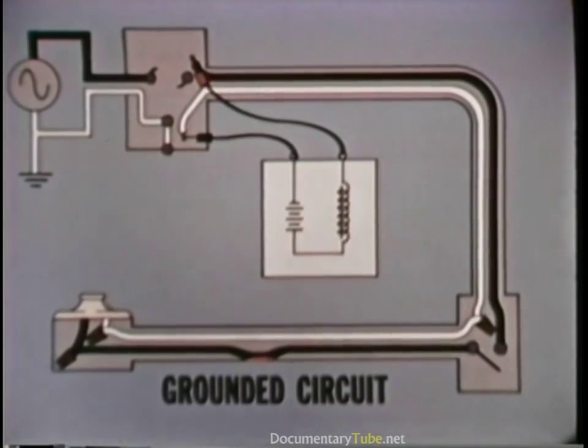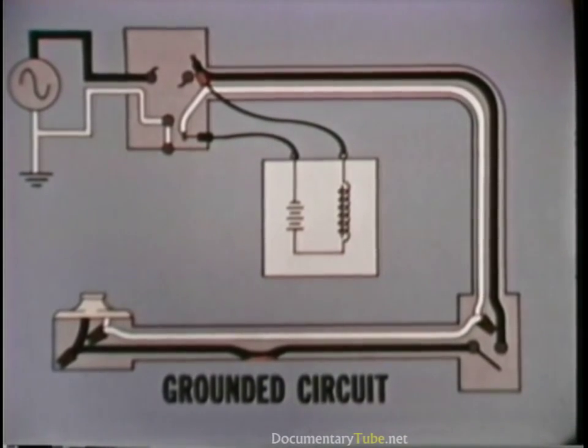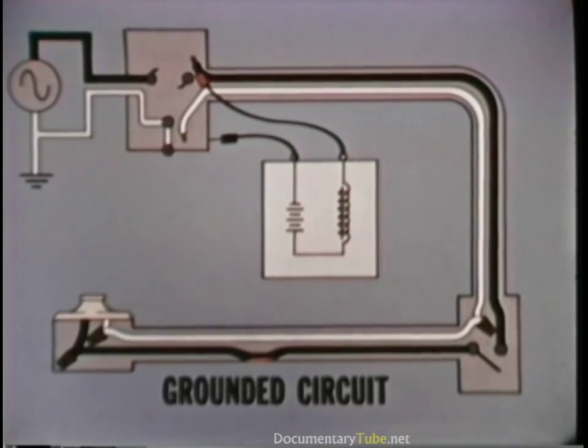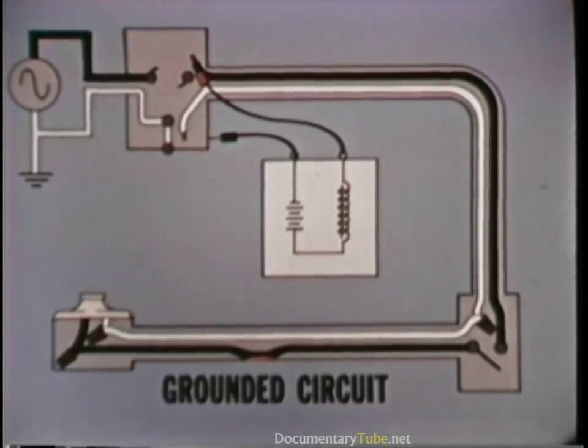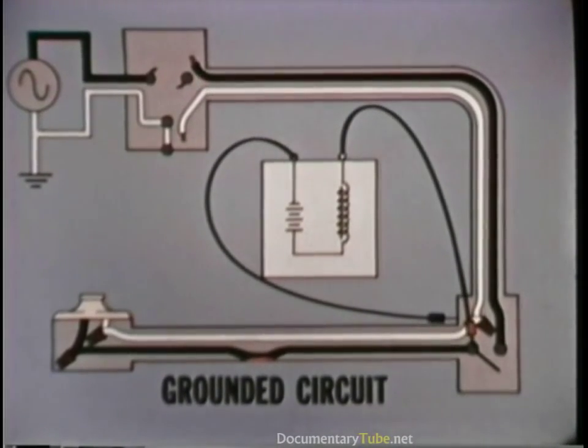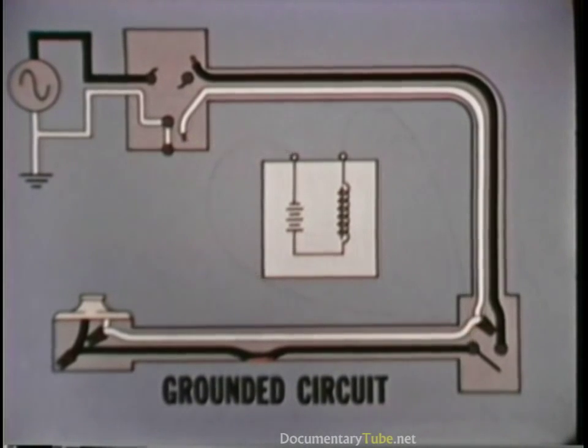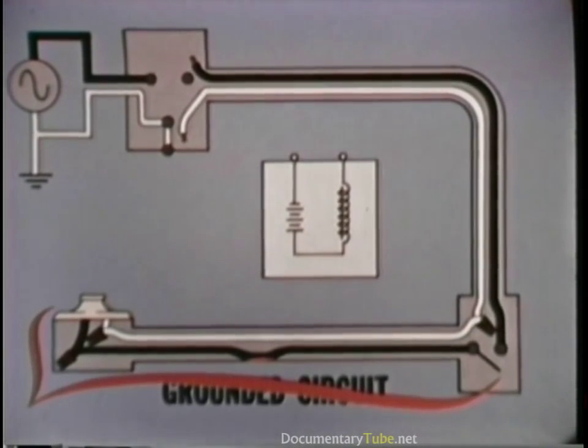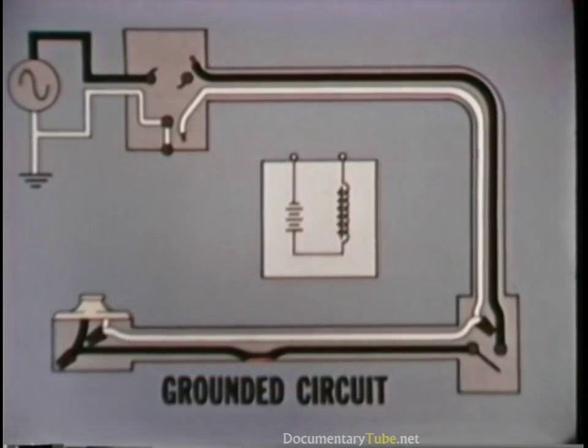First, checking between the two conductors indicates that there is no short circuit in the first section of the circuit, and there is no continuity between the hot conductor and ground in this section. However, between the hot conductor and ground in the second section, there is continuity. Since this is the last section, the testing is complete. In a longer circuit, the diagnosis would be confirmed by checking the next connection.